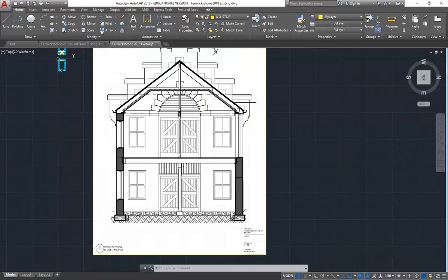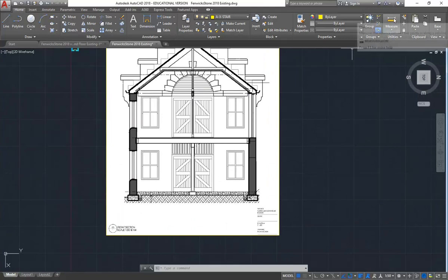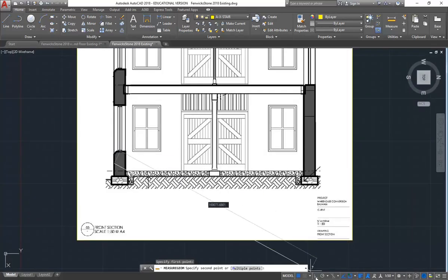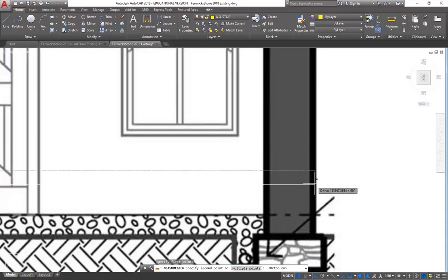Now, with the scale tool, there is a way of picking points on the screen and using that measurement. But what I usually prefer is to measure again and then type the measurements in. I'll give you both examples. Firstly, I'm going to use the measure tool again, and then zoom right in and click a point on the left of my building, in the middle of that wall, and then a point on the other side of the wall, the opposite wall.